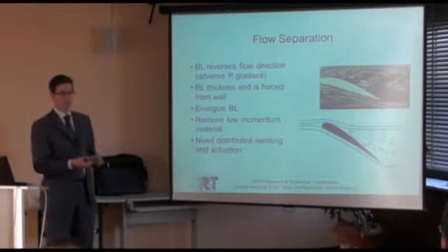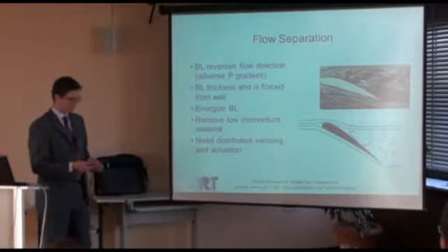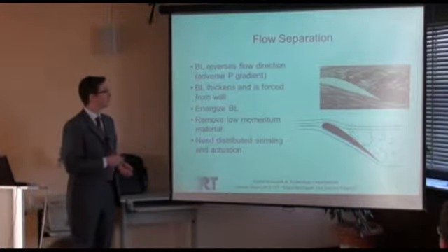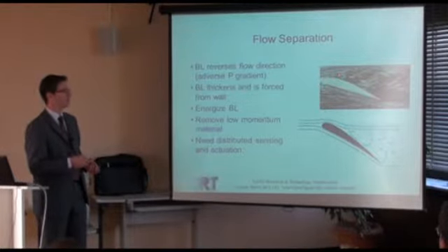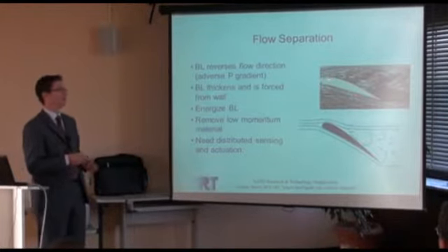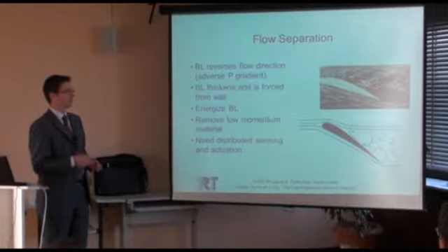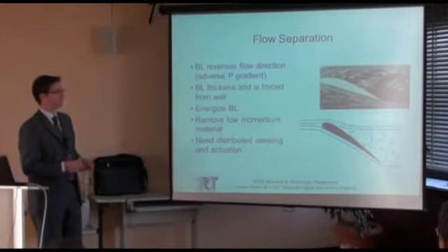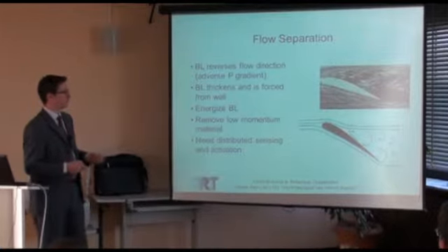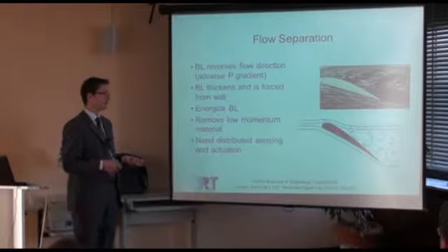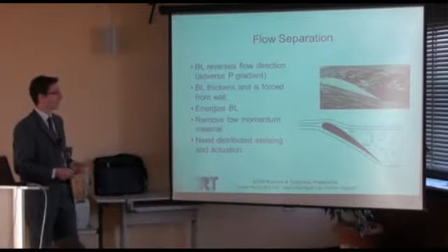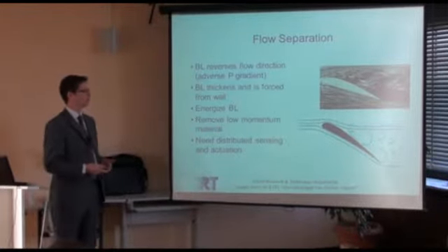So we've got flows everywhere, and these flows have boundary layers on surfaces, and they tend to detach if there's an adverse pressure gradient, meaning that the pressure downstream is higher than the pressure upstream. So the flow detaches, which means that basically there's a boundary layer which thickens up and then detaches from the end wall.